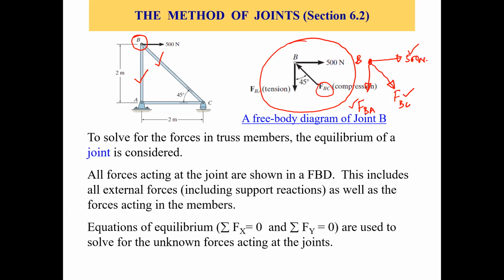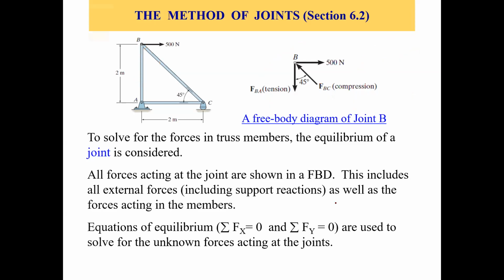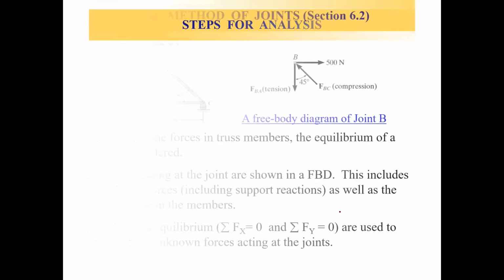So if you can visualize that, then you can say that it's a compression. But if not, then just take tension in all the member forces, right? Assume all the member forces as tensile forces, like what we have done here. Okay, so that's how you are going to do with the method of joints.